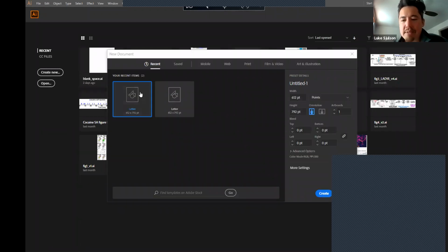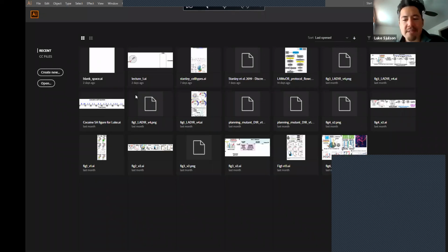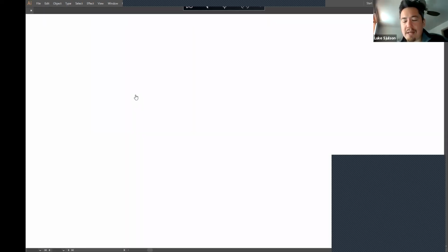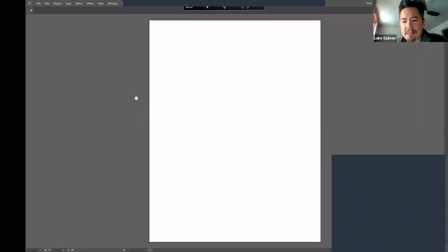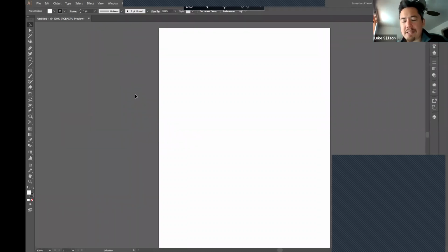They have this sort of thing where there'll be one random bit that's wrong every 60 gigabytes or something. I don't know the exact number, but that number stayed largely constant over the years. And the speed at which they read and write data has stayed roughly constant. So in reality, hard drives have actually gotten slower and slower, in the sense that the amount of time it takes to read 1% of a drive's capacity has gotten longer and longer.